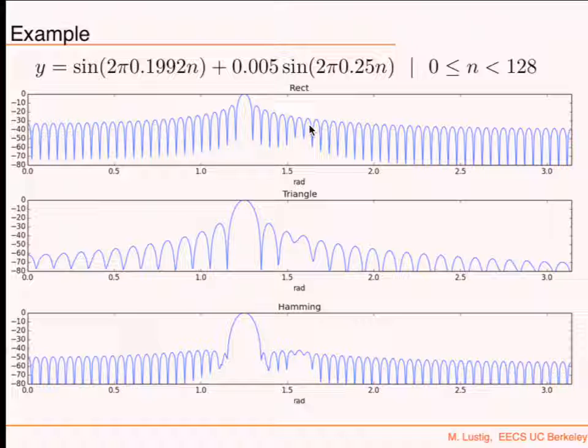I'm not talking about the case of noise here. There's no noise. It's perfect, just pure frequencies. No noise, and I cannot see it. That's a problem. If there's noise, that's even more disturbing. If I use a triangular window, there's a bigger disturbance in the force. When I use a Hamming window, still not there.